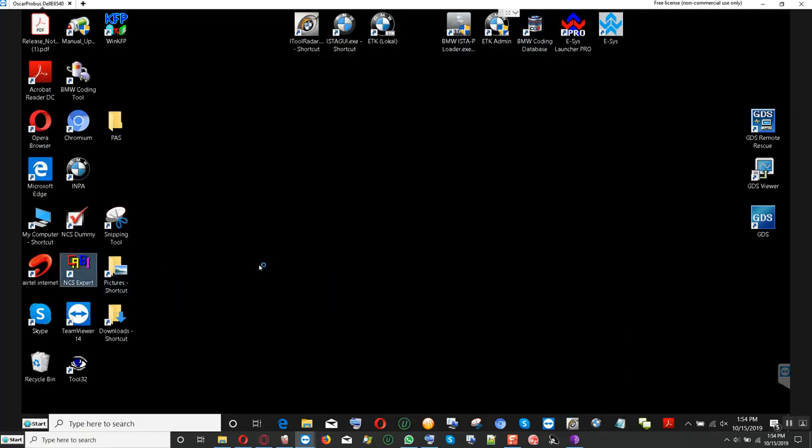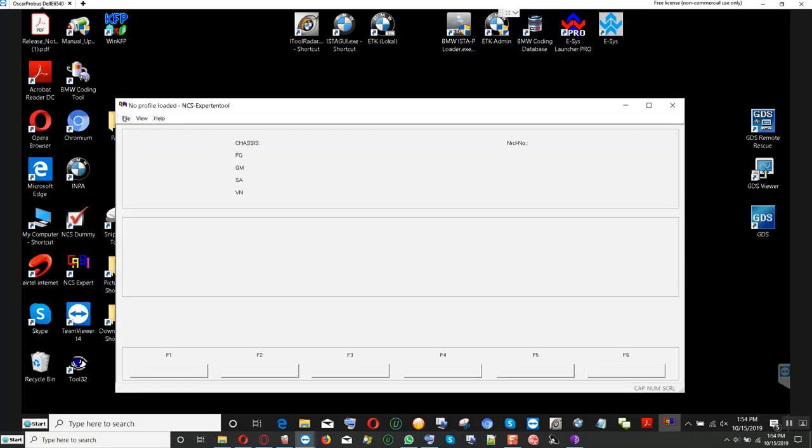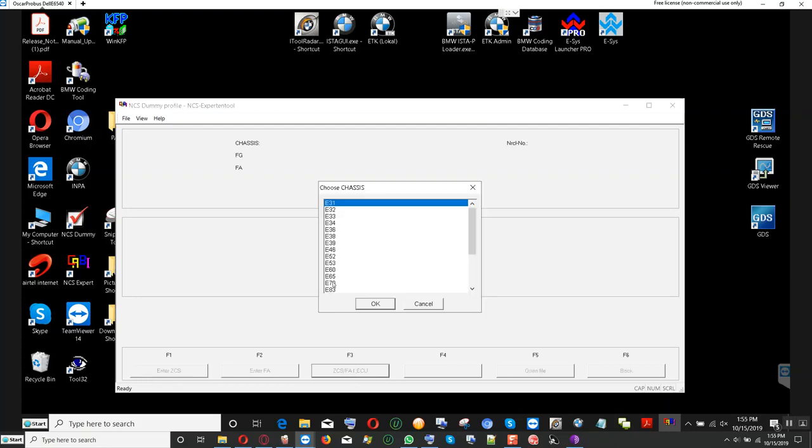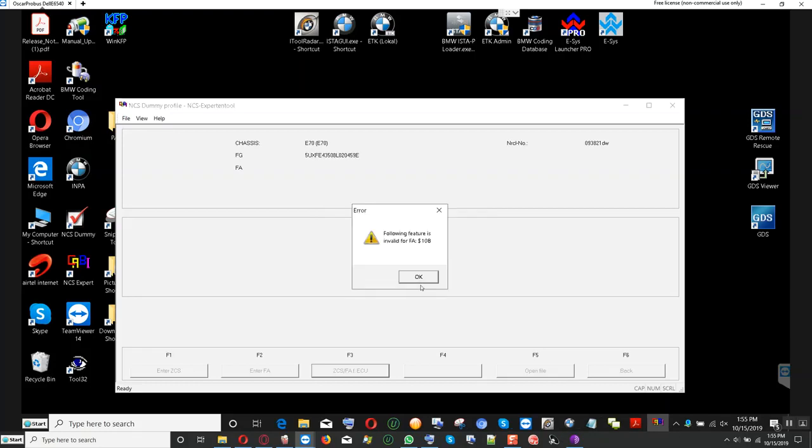We'll go back into this again. NCS Expert. Load that profile. Choose NCS Dummy. F1, F3, E70. You choose the CAS now. Watch the same error come back. See there? Invalid for FA, this one. So I'm going to try to remove it and see what happens.